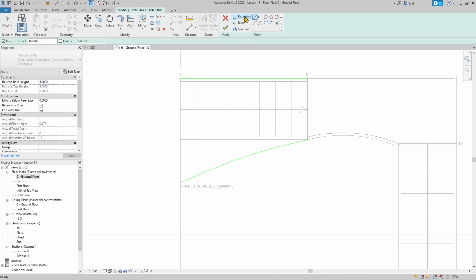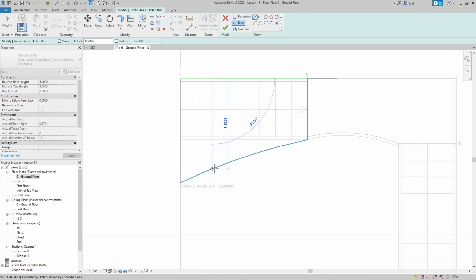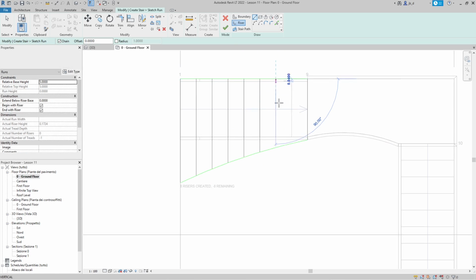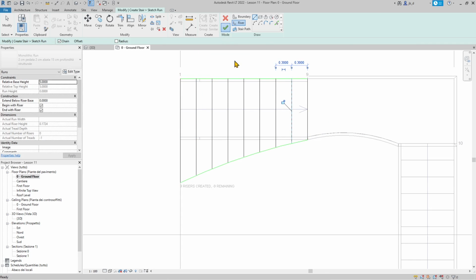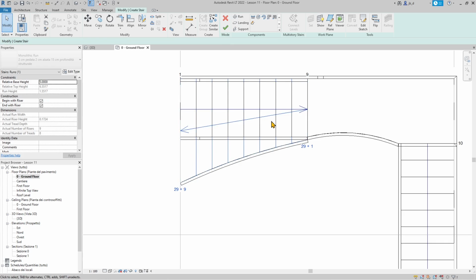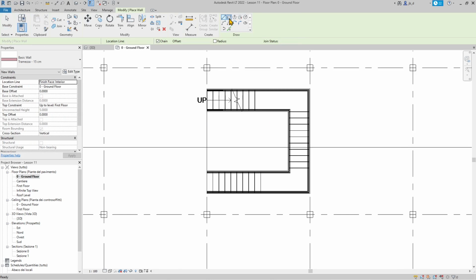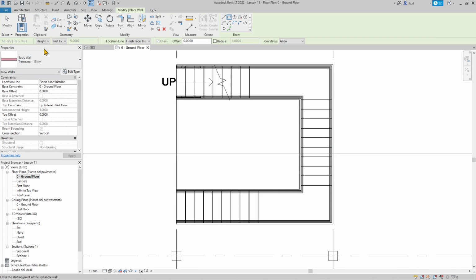And then you can see here you have boundaries, you have risers. Now risers will go here and it's gonna start to count. So it's telling you that you have 2 risers, so you need to place the others like that. So I'm following the stairs that are underneath as a base to draw my customized one. Now remember, everything needs to be closed, and then you say okay, and it's gonna create it. So you can create pretty strange stairs there if you want.